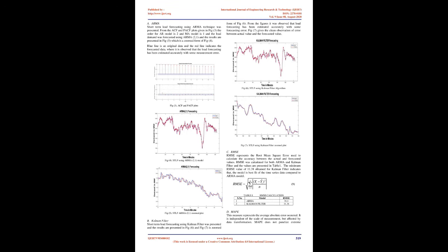The final estimation algorithm of KF resembles that of a predictor-corrector algorithm for solving numerical problems 13,16. Where Y_t is a system state of order n×1, F is the n×n state transition matrix, Z_t is the measurement vector of m×1 order, H is the output matrix of order m×n, W_t-1 is an uncorrelated white noise, V_t-1 is an m×1 uncorrelated white noise having zero mean, K_t equals the Kalman gain at time t, Y_t^- equals the priori state estimate at the previous time interval, t-1, Y_t equals the posteriori state estimate at time t, P_t^- equals the priori estimate error covariance at the previous time interval,